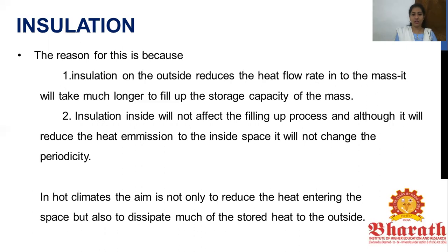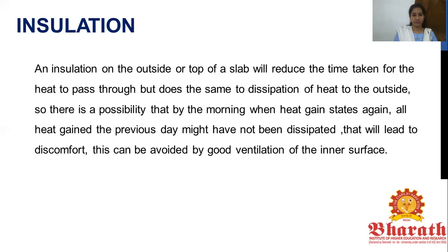The insulation inside will not affect the filling up process, and although it will reduce the heat emission to the inside, it will not change the periodicity. So in hot climates, the aim is not only to reduce the heat entering the space, but also to dissipate as much of the stored heat to the outside.